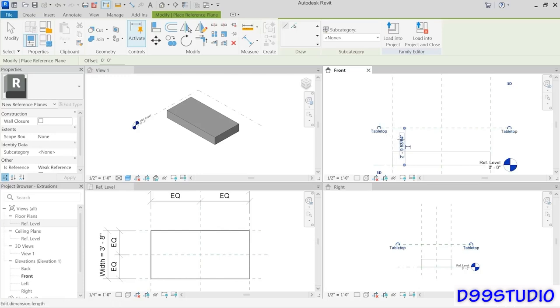And then for the dimension, I'm going to click right in there, and in imperial, I want to do 2 foot 7 inches. If you're working in metric, you can put 787 millimeters, 787. Now keep that dimension active, and there's a little make this temporary dimension permanent icon right here. I'm going to click that.